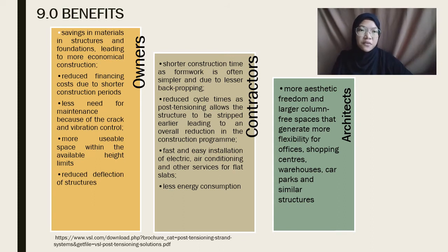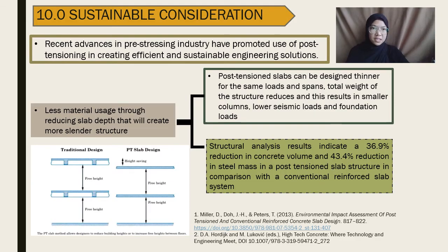For the architects, it will be easy for them to express their ideas as they have more aesthetic freedom. There are a lot of sustainable considerations that were discussed during the designing phase of constructing a post-tension concrete. Recent advances in the pre-stressing industry have promoted the usage of post-tensioning in creating more efficient and sustainable engineering solutions. This can be achieved as less material is used through reducing the slab depth, which will create a more slender structure.